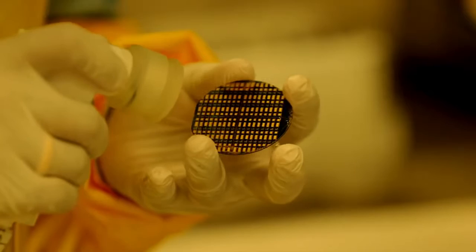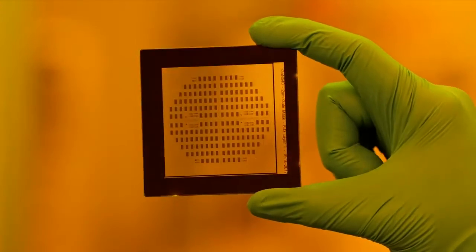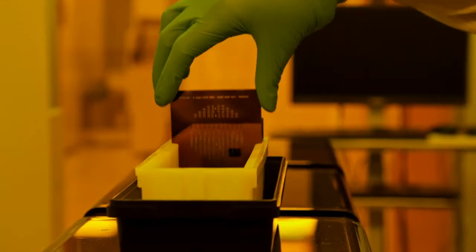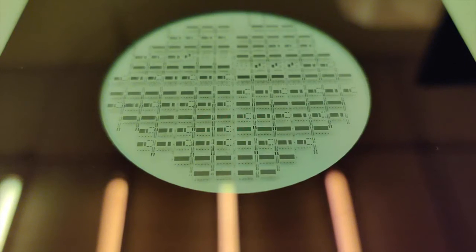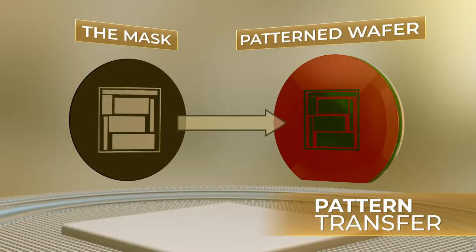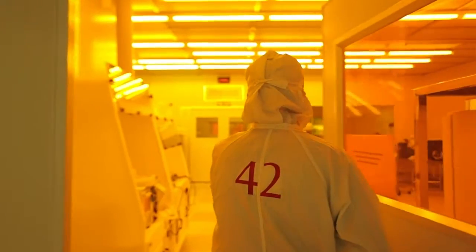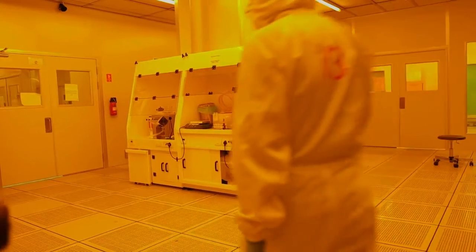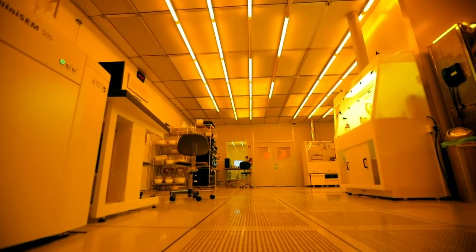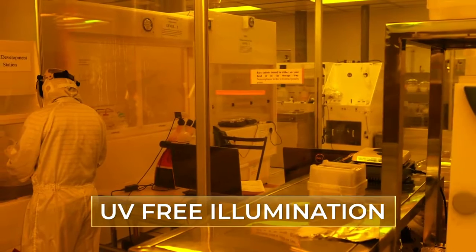The first step involves putting down metal pads at specific points on the wafer surface. A mask is first created on a chrome-plated glass plate. It is now time to transfer the pattern that is there on the mask plate onto the wafer surface. To do so, we will now travel from the chemical vapor deposition reactor to the lithography bay. Lithography means writing with light. You will see that the bay here is flooded in yellow light. It is ultraviolet, UV-free illumination.